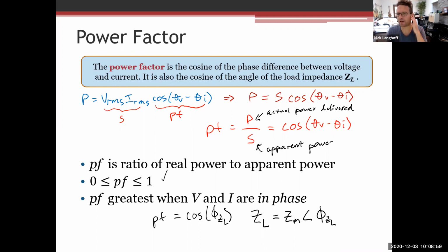So is AC power as efficient as DC power? I think the question would be, well, what voltage? What's the peak DC voltage? Let's say it's 10 volts. Okay, and then what's the AC voltage? Is it the peak AC voltage, V peak is 10 volts, or is it VRMS is 10 volts? And it should be VRMS, right, to compare apples to apples.